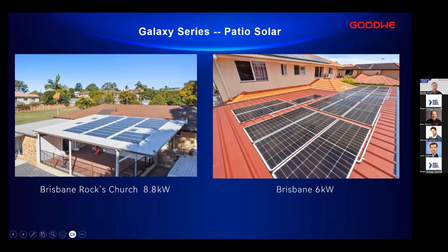This patio is made up of flat sandwich panels. So we put ventilation tubes underneath and glue straight away on the rooftop. And this is another case for a typical tin roof sheet, a corrugated roof. As you can see, there are no mounting structures required. We just glue straight on these ribs of the patio.